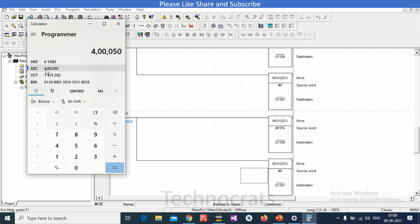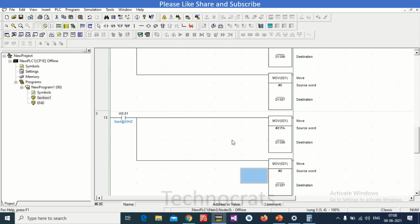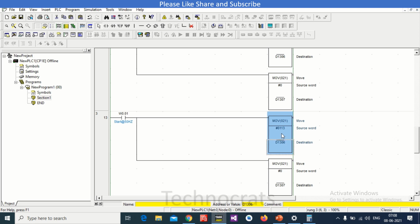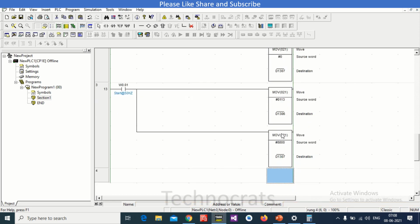We will use 50 Hz here. So 1388 is your hex code, so I will use 13 and the other part is 88, I will use 8800. Okay, so this is how you can write your start command and frequency.